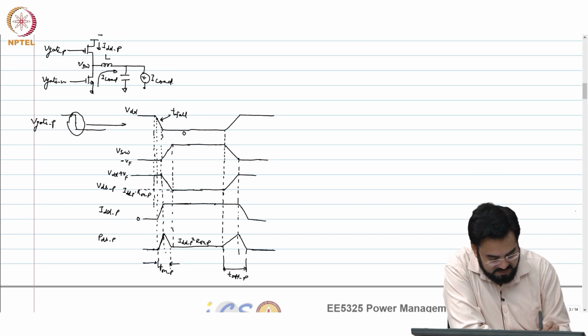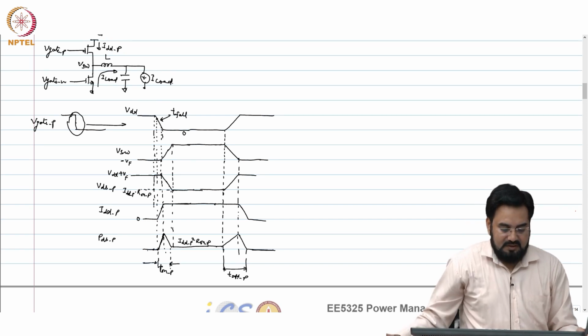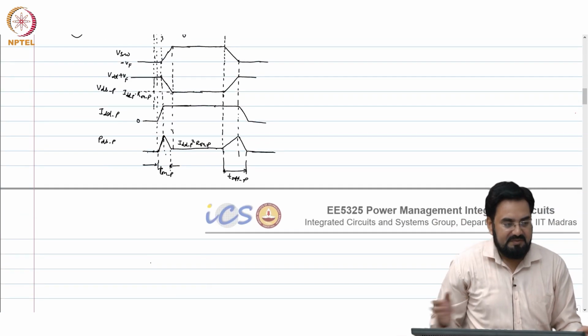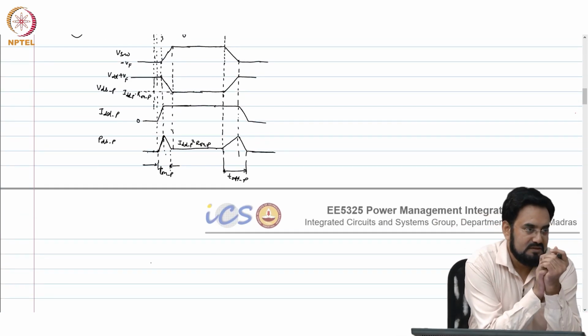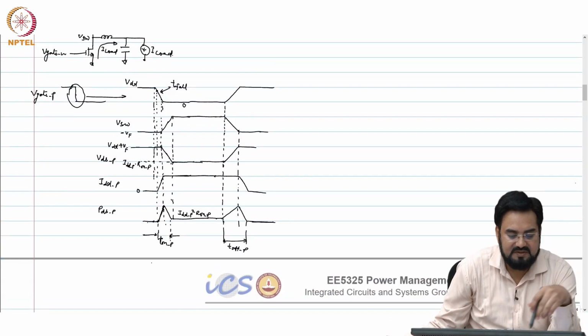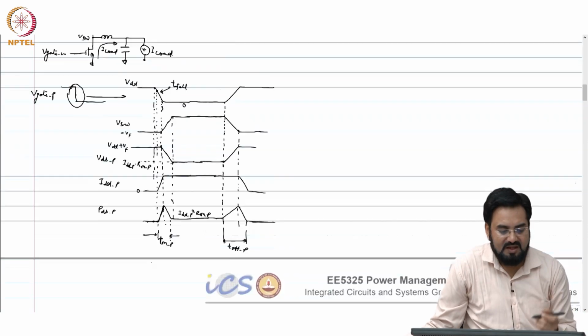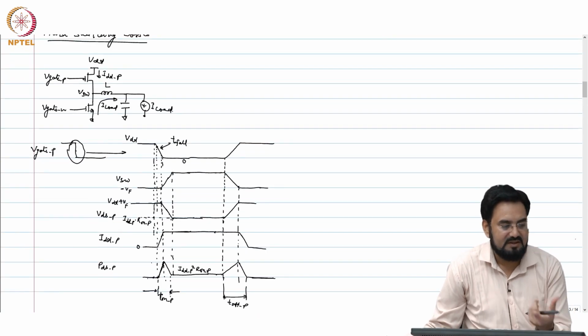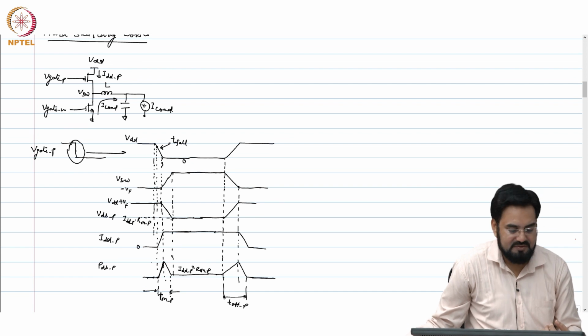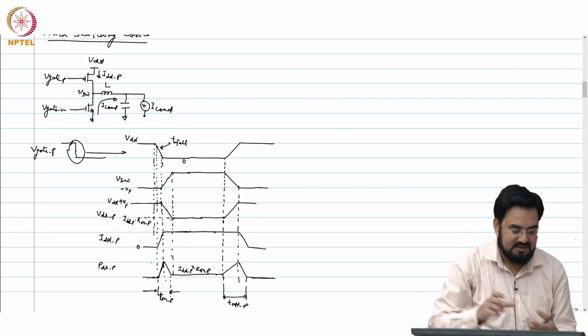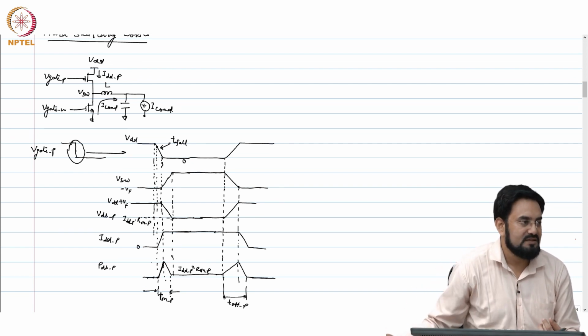Let us make it small. Okay. So, they may be different, T on and T off might be different, because your rise and fall of the gate might be different, correct, and you do not know at what point exactly your diode will turn on, but usually the VDS voltage is almost full when it turns on.